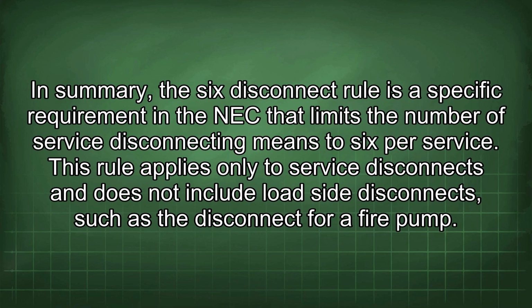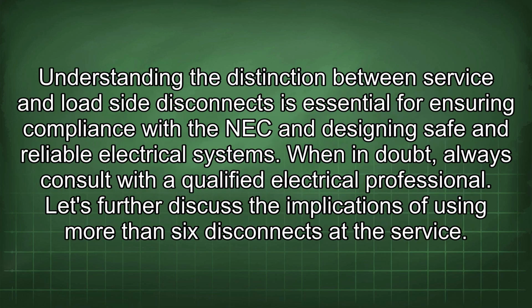In summary, the 6 disconnect rule is a specific requirement in the NEC that limits the number of service disconnecting means to 6 per service. This rule applies only to service disconnects and does not include load side disconnects such as the disconnect for a fire pump. Understanding the distinction between service and load side disconnects is essential for ensuring compliance with the NEC and designing safe and reliable electrical systems. When in doubt, always consult with a qualified electrical professional.